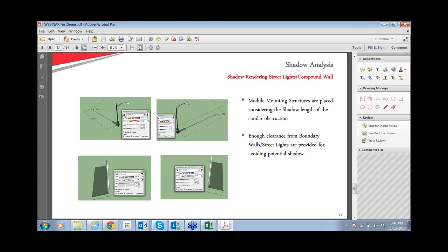So if you see, the shadow is on the eastern and western part at some incline angle. This angle you can find out from Google SketchUp Pro or even from PVsyst, and then you can mark these lines on your array layout and keep the area falling within this shadow line as vacant space, and then plan modules in the rest of the areas.